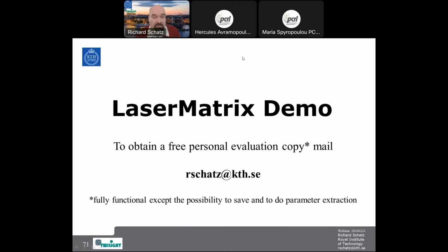In fact, there are two ways of doing it. Either to use the chirp grading function, then you are limited to certain functions, like you can have a sinusoidal variation, quadratic variation, or a polynomial variation of your grading, or exponential variation of grading, and you can do it in several sections. Otherwise, you can also have a complete possibility to define your grading from scratch, layer by layer, and then tell the program to repeat this layer stack this number of times.